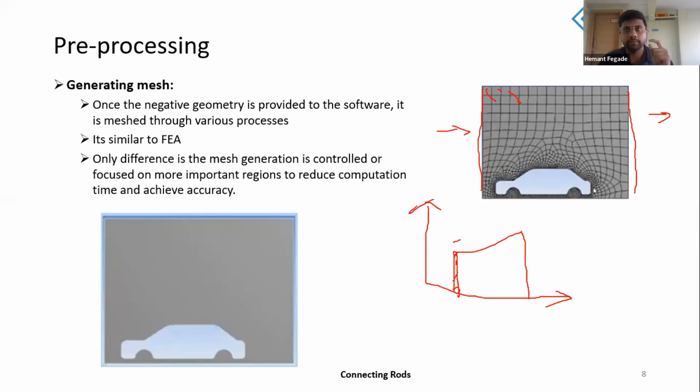Now, the amount of time it's going to take to solve an infinitesimally small element, with all these properties, is going to be much larger as compared to solving on a bigger element. There is a lot of computation involved, because you are not only reducing the size, you are improving the order of these equations. All of these properties are defined by partial differential equations, and there are going to be higher order terms like squared, cubic, fourth order, fifth order. That's how these properties are going to be defined.